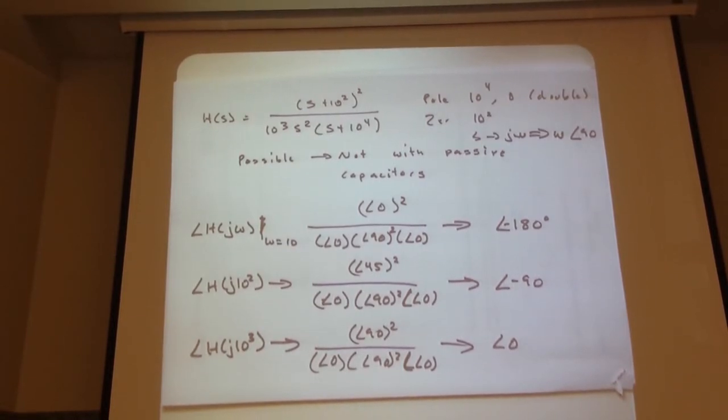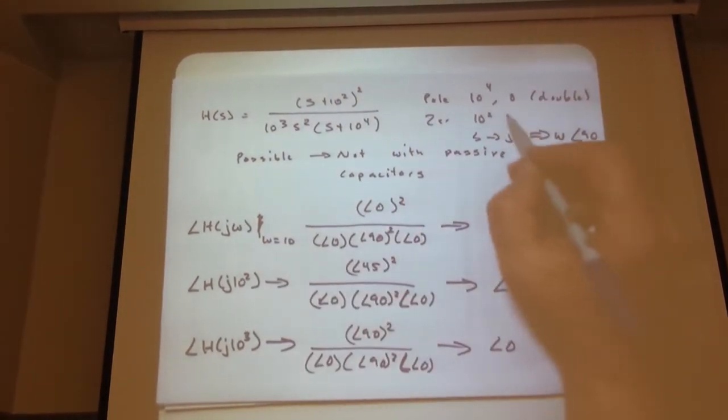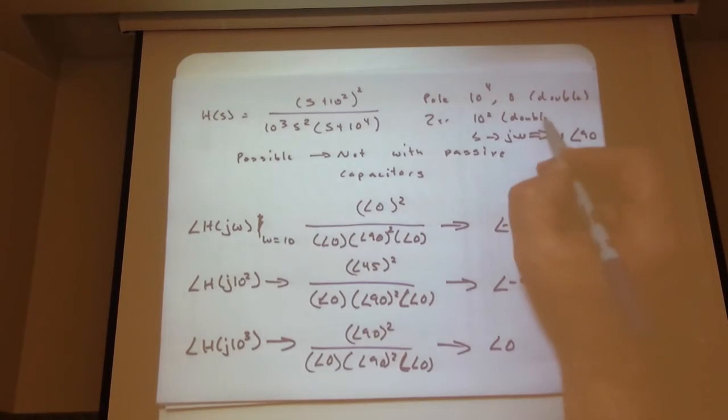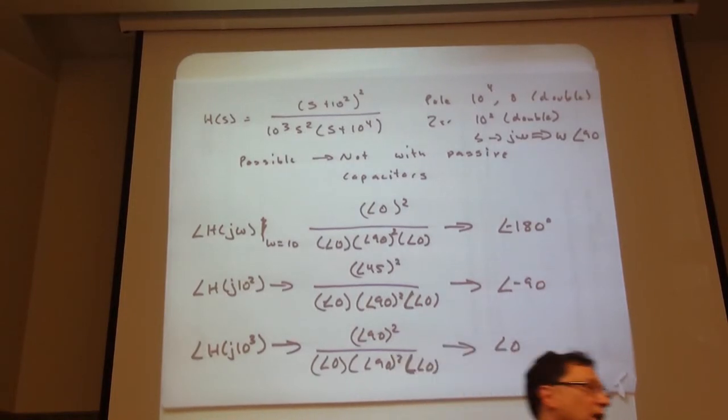If we cross a 0, what's the absolute change in phase angle? 90 degrees per order. So this was a double 0, right? We have a square. That's a double 0, which I should have written down. You should have said something. Should always indicate that. That was a double 0, so plus 180 degrees of phase over 2 decades.